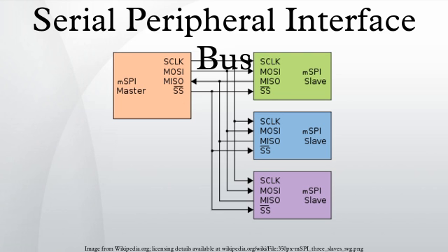Interrupts. SPI devices sometimes use another signal line to send an interrupt signal to a host CPU. Examples include pen-down interrupts from touchscreen sensors, thermal limit alerts from temperature sensors, alarms issued by real-time clock chips, SDIO, and headset jack insertions from the sound codec in a cell phone. Interrupts are not covered by the SPI standard. Their usage is neither forbidden nor specified by the standard.